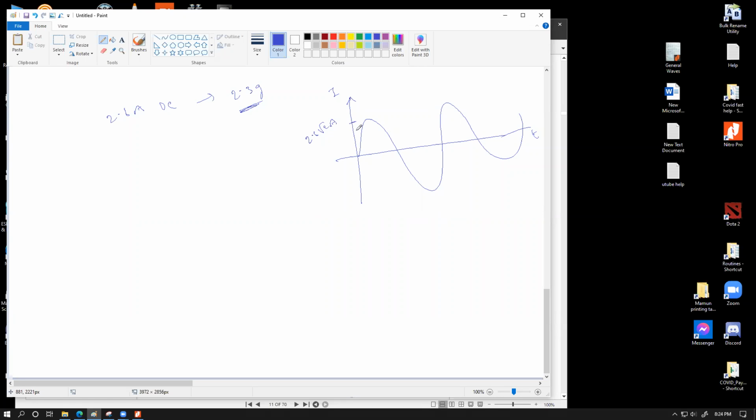That's part one. The second thing is that for an AC supply, the current is in one direction and then in the opposite direction, so you're going to have both an increase and a decrease of the value. You're going to have a bidirectional change. If your original reading was, let's say, 100 gram, for an AC supply the reading is going to increase for half the cycle, reach a maximum, and then decrease from 100 gram on the bottom side. So you're going to have double the variation because the current is changing direction.